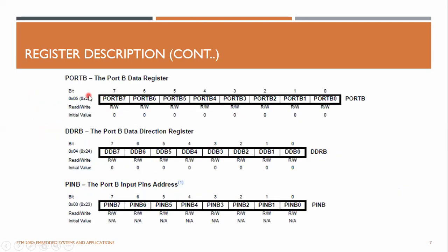And these are the other registers that I have just discussed. If you take individual ports, there are different dedicated registers. DDRB represents port B. So if you want to do something to port A, you have to deal with the port A register, right? Not port B. So DDRB is the data direction register of port B. This is how it looks. It's an 8-bit register. All of them are read-write.